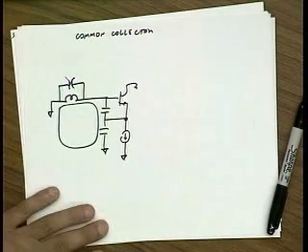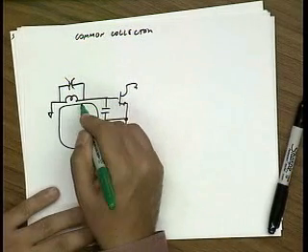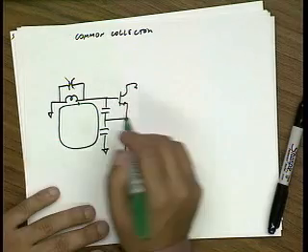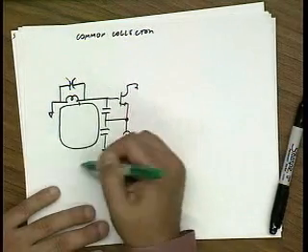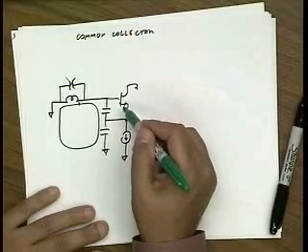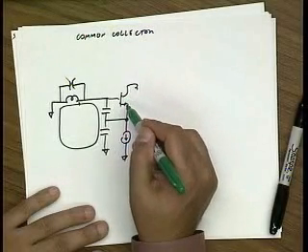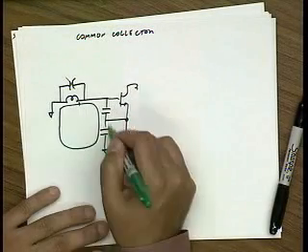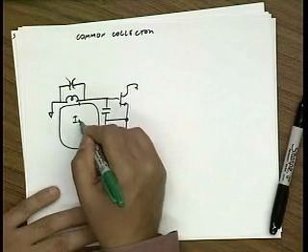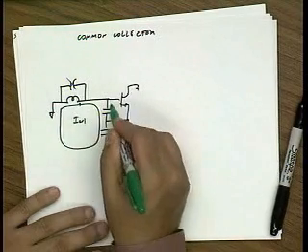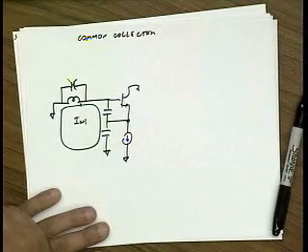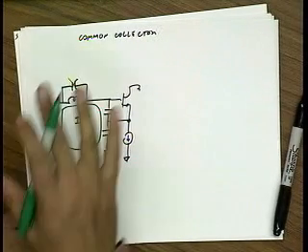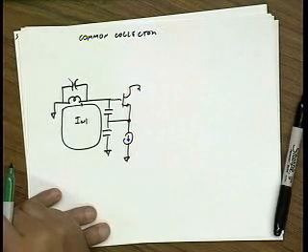So you get rid of this extra component, and then the circuit becomes very simple to think about, because again, under a high Q assumption, this tank current is much larger than the current that's being injected by this transistor, and so for all purposes, I omega 1 flows through here and produces an input voltage and an output voltage. Okay? So same kind of analysis we can apply to this oscillator.